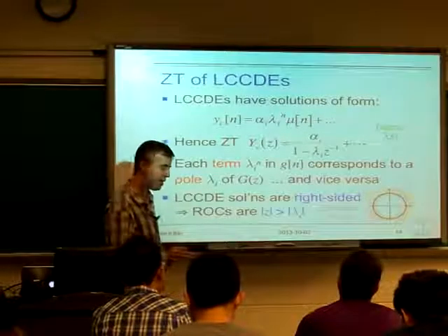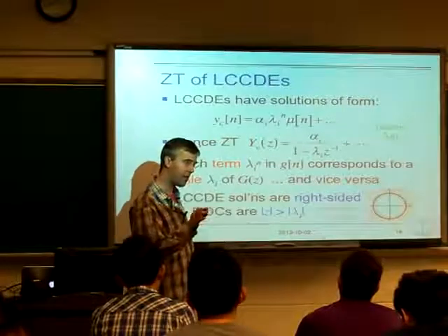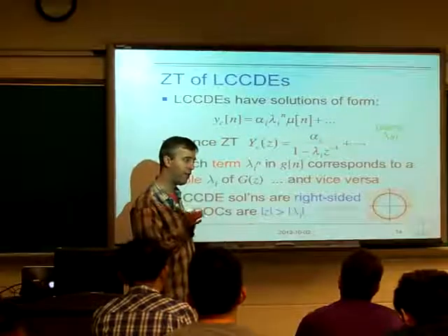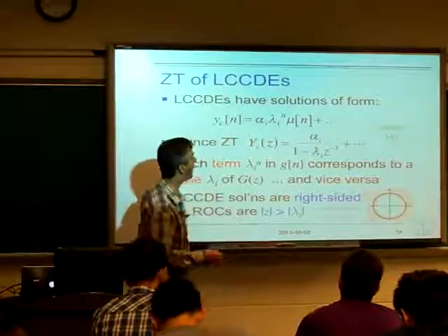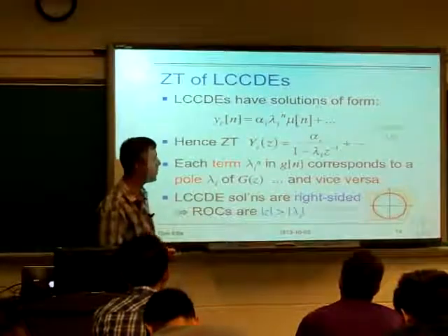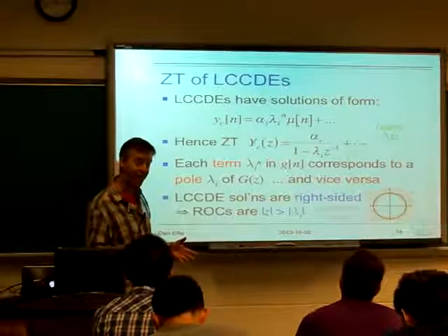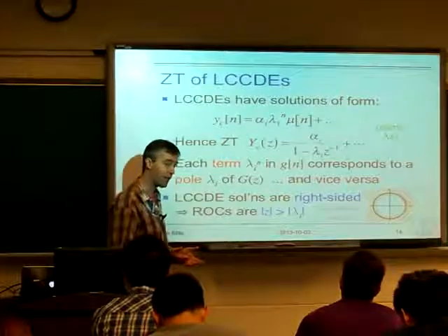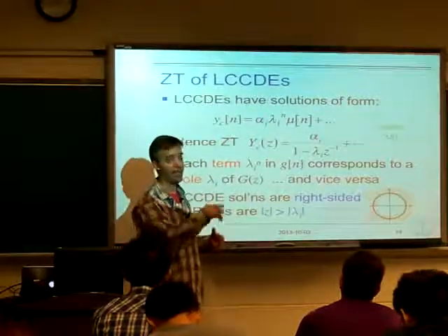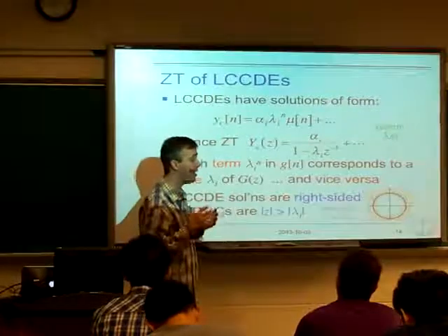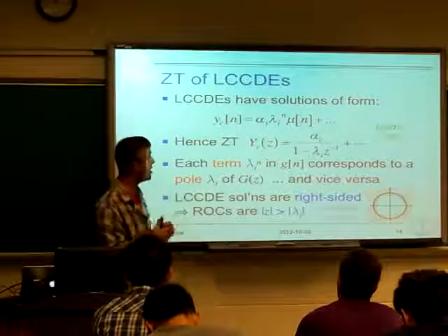Okay, so we've got this z transform. It seems like it's going to be a quick way to understand something about the Fourier transform, the behavior in the frequency domain. We've got systems that we can build easily, which are systems defined by these linear constant coefficient difference equations. So systems where we basically just have delays, gains, and then feed forward or feed back. With a finite number of delays, we can express them in terms of these LCCDEs.